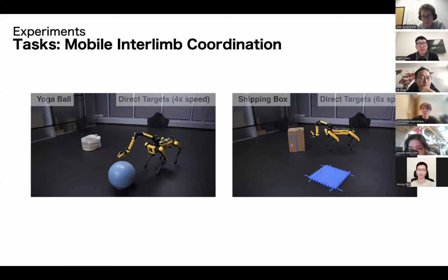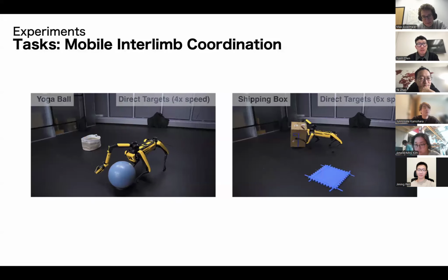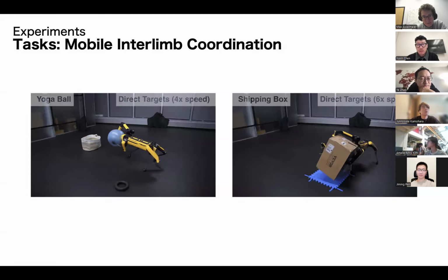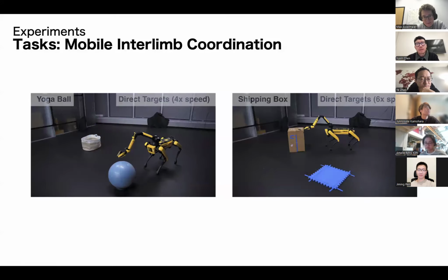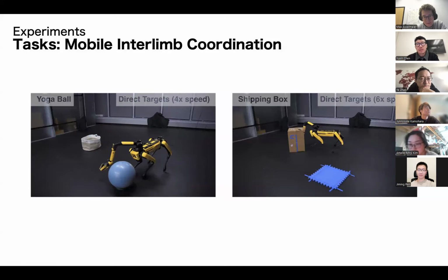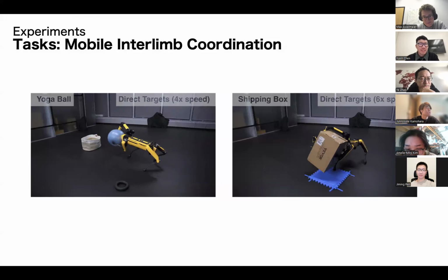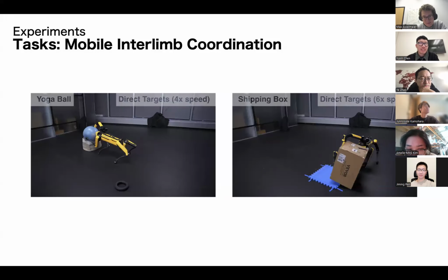You can see the motor current change, which gives a brief estimation. We may not need to explicitly attach a tactile sensor to the robot, but for more precise tabletop manipulation, I do think adding the tactile sensor is much more informative.